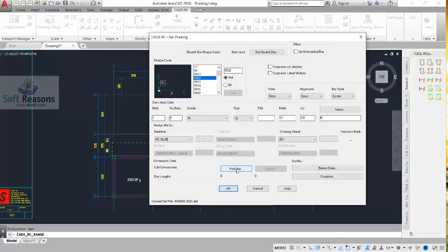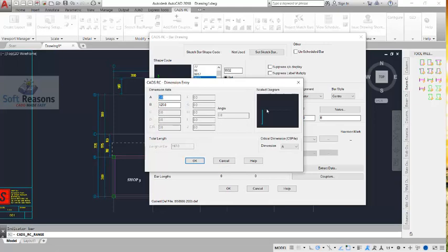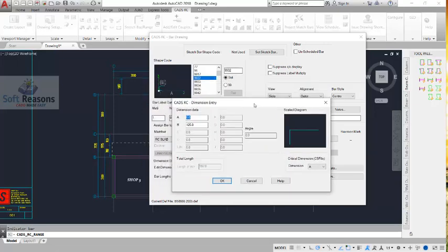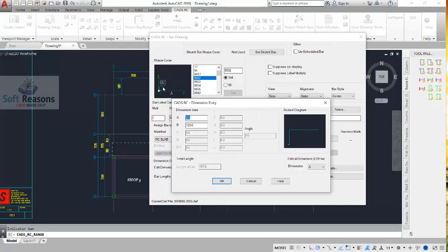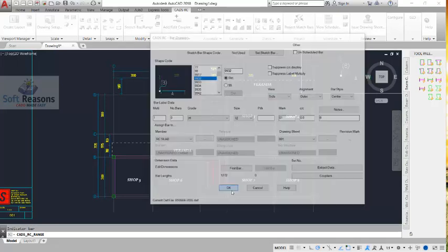All right, so if you click in this first bar option right there, this is what you have. Okay, so you can see on the bar the A is the length of the bar. Okay, that can be determined later, and then you can see the B right there. Okay, which is the return length, which is the top bar length. All right, so over here you can just key that in to be 1200 right there, just like this. Okay, so for the A, you can leave it at 0, and you can always specify or adjust it later. So click on the OK options right there. So after which, click on OK again.